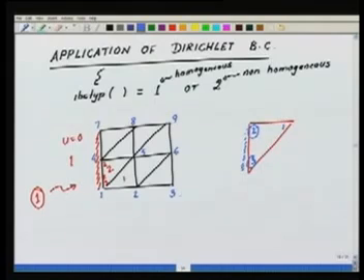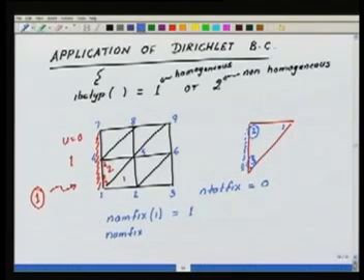So immediately I start a counter and I start counting the number of degrees of freedom which have to be set to 0. So I start with the total number of fixed degrees of freedom equal to 0, initialize. Now I loop over these edges, and for the name of the fixed node, I increase the counter. For example, the first one will be equal to the global node 1. The name of the second node which is fixed, from this element, comes out to be the global node 4.